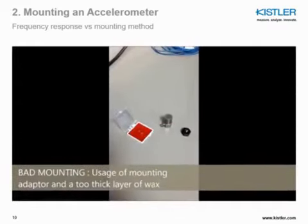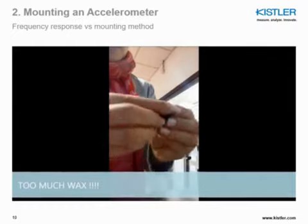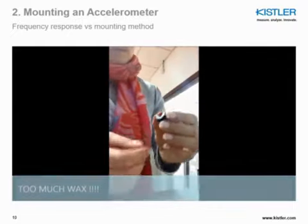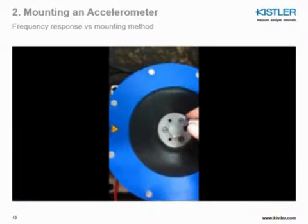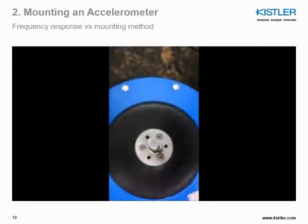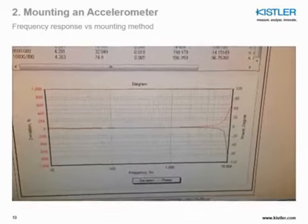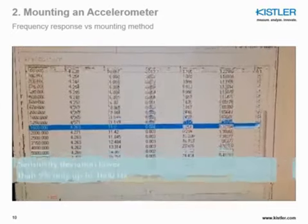Now, this is a bad example. We put way too much wax at the bottom of the sensor, plus we have this base. So we have 2 major mechanical filters in there. Here we'll see that the response at 5% will then only be at 1600 Hz.